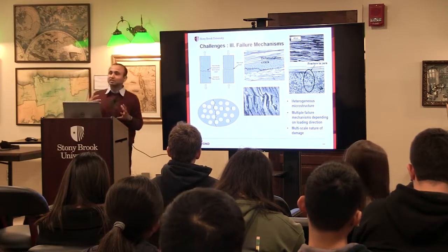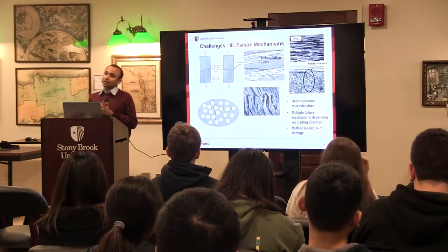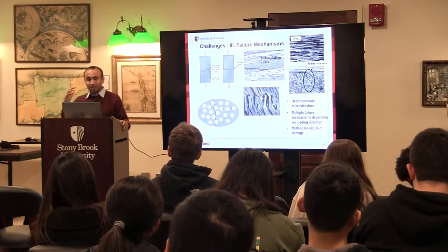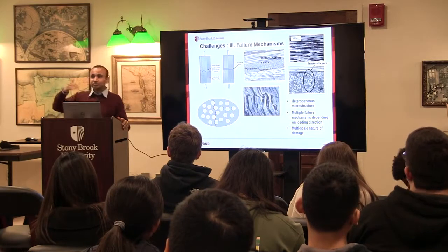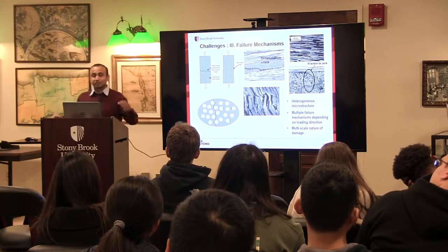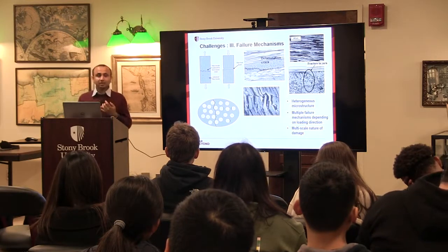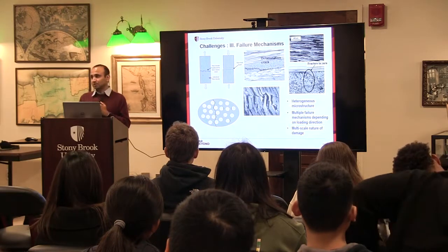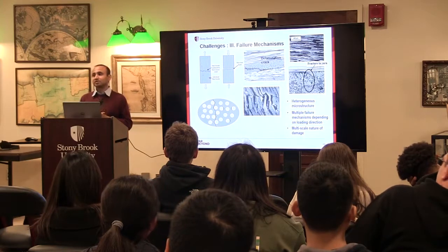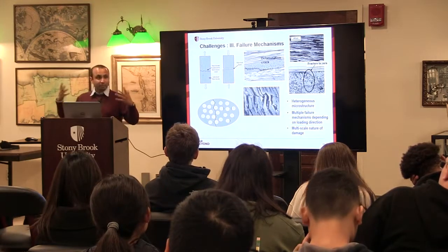And each of these mechanisms dissipates a different amount of energy. So that presents another challenge for composites. We need to first of all characterize the energy under each of these different modes, which is again different. So this is challenge number 3, that the failure behavior is very, very complex. It consists of multiple mechanisms at different scales, and each of these mechanisms dissipates a different amount of energy, which you need to effectively predict.